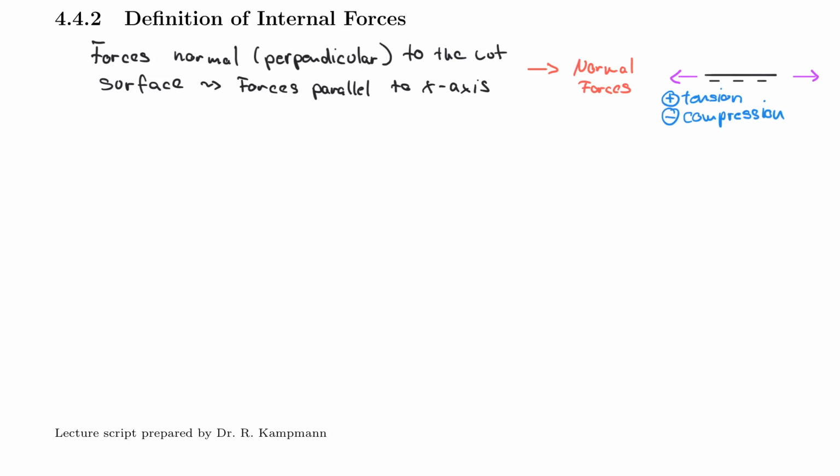And so you may understand that engineers use this very effectively, because every column by definition has to be in compression. Otherwise it would not be a column, right? A column is something that carries vertical loads. And so engineers know by default that the normal force in a column is negative. And they use that effectively to communicate if it's in tension or in compression by means of the normal force.